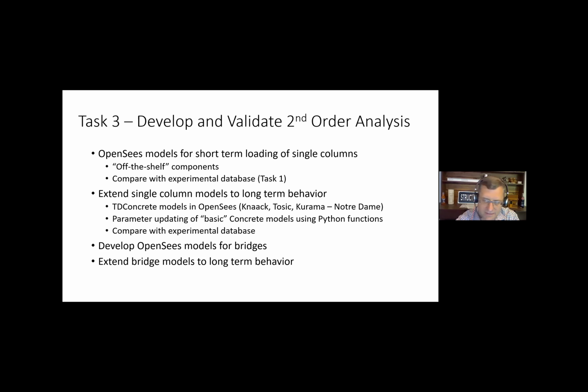So just modify the parameters of, say, Concrete01, and then look at the analysis as it marches through years of time, if you will. And then, of course, compare with the experimental database for the experiments that involved long-term loading. Then develop the OpenSees models for bridges and extend the bridge models to long-term behavior as well.